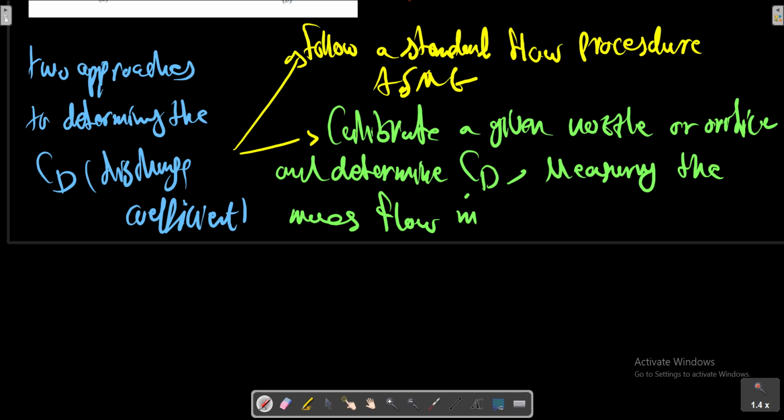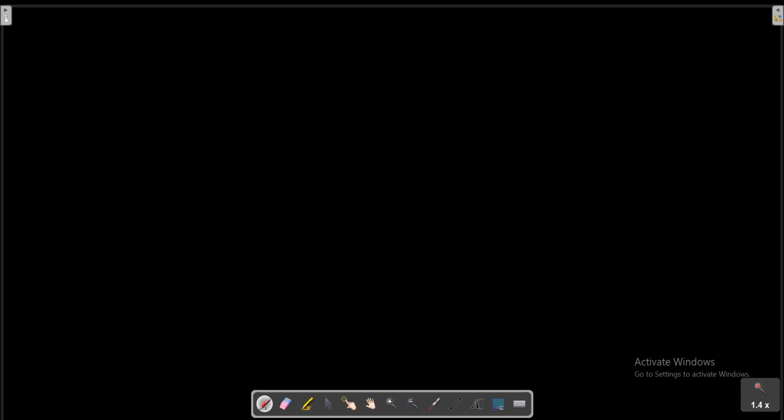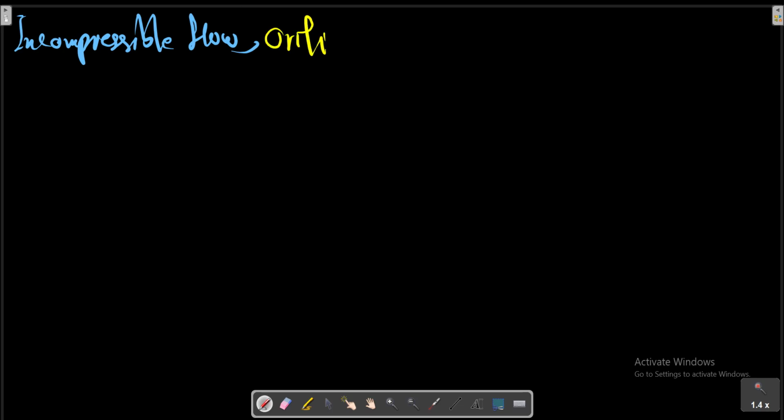For incompressible fluid flowing through an orifice, the ideal flow for a given pressure drop can be found by the procedure outlined in the previous section. Actually, it is advantageous to combine equations 17 and 21 to give the following relation, which is valid for reversible flow.